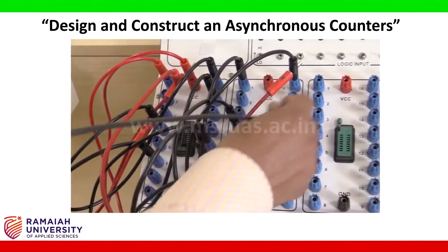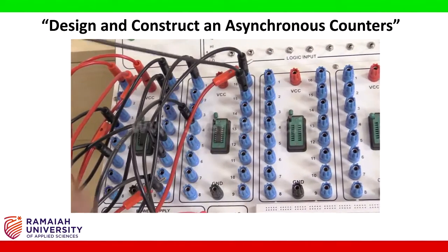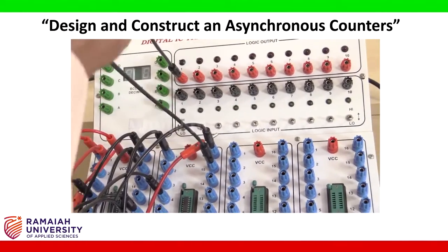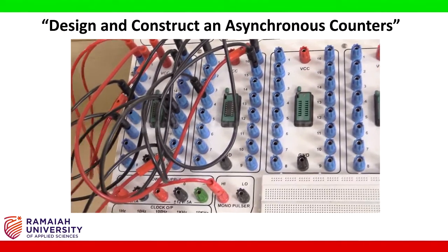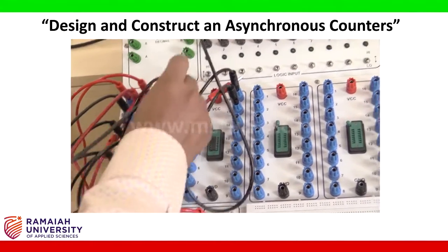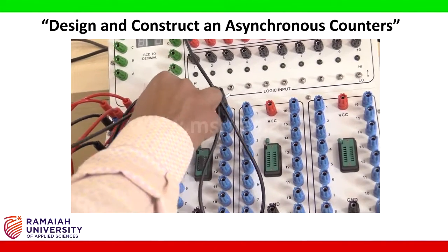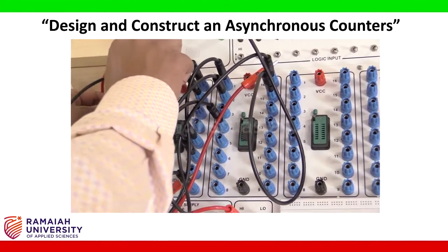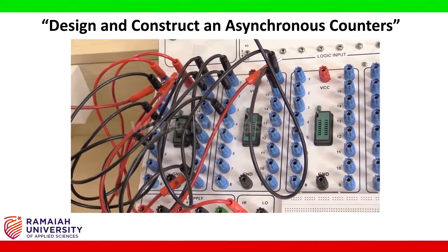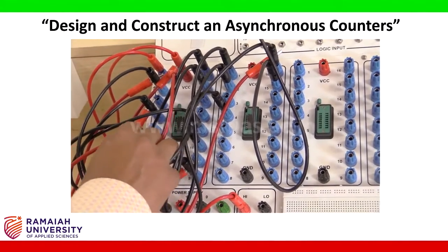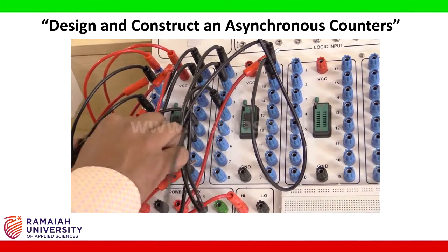Next, pin number 15 is output QC. I am connecting here output QC, and pin number 2 of both IC bases are shorted, and that is also shorted with pin number 7 of the first IC base. From that it is connected to VCC again.